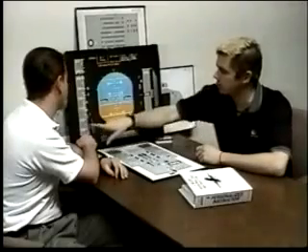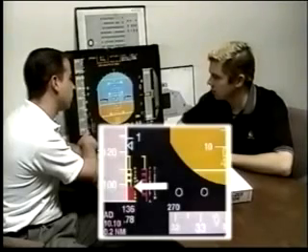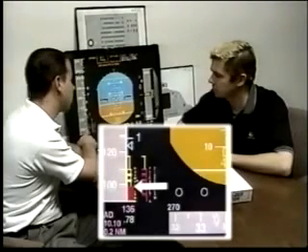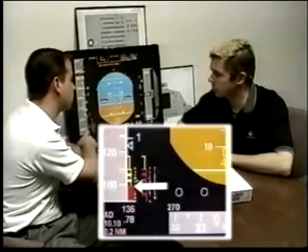If you're in alpha protection and you let go of the side stick, what will occur? When I let go of the side stick, the nose will fall to maintain the top of alpha prot. So what positive input is required to get out of alpha prot? I'd have to push forward on the stick. If you were to hold full aft stick, you get to the red tape, which we call what? Alpha max. Okay, and what are you commanding in alpha max? That's the maximum AOA that you can get with full aft stick.